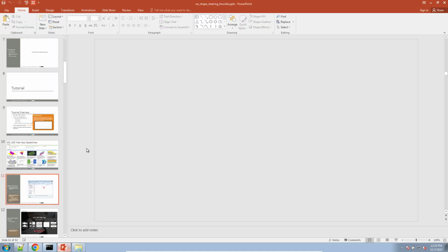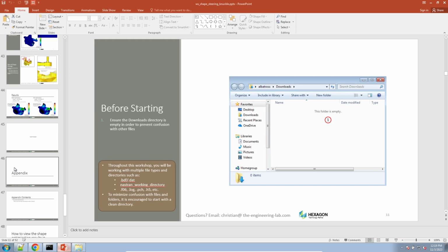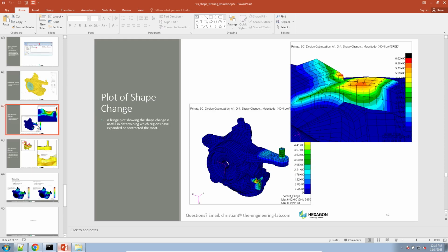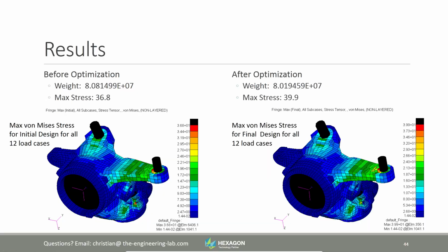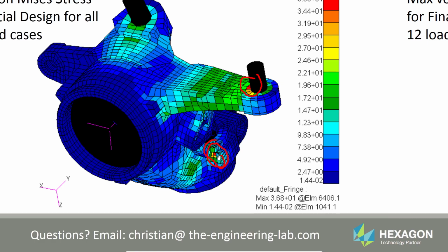If you look in the PDF document, you'll see that this region and this region of the initial design have a high stress concentration, if you will. What we want to do is maybe modify some of the geometry here, some of the boundaries, so we make sure that the stress is within our allowed limit.